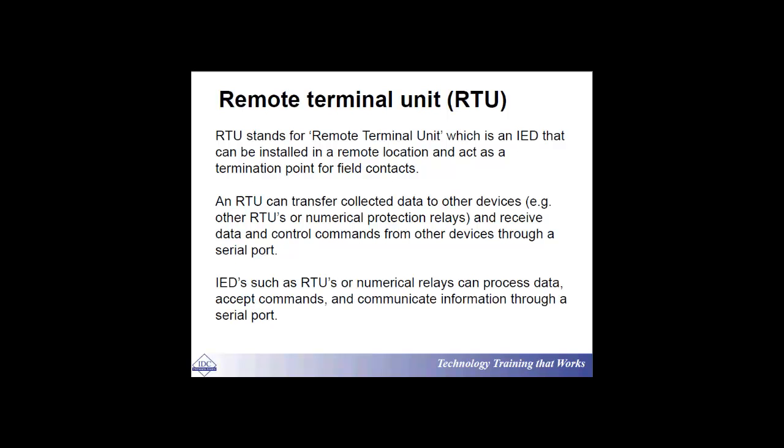So as I said, the remote terminal unit is the point where you receive the information from the field devices, such as the CTs, such as the VTs, such as the sensors, the transducers that control pressure, control height of a liquid, control frequency, control vibration, control temperature of what? Of transformer winding, for example, things like these.